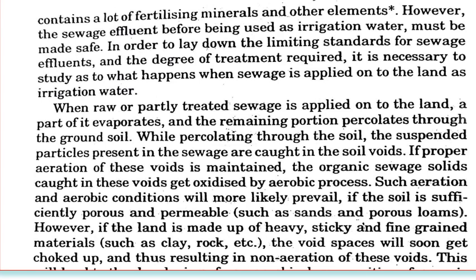The same slide which was explained to you. So, see, when the raw or partially treated sewage is applied onto the land, a part of it evaporates and the remaining portion percolates into the ground through the voids which are present in the soil. And the remaining solids present in the sewage are caught in the soil voids.